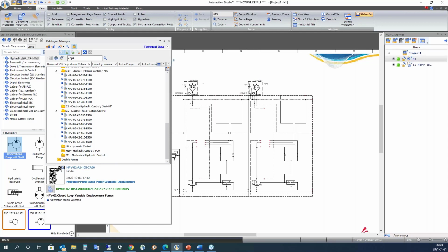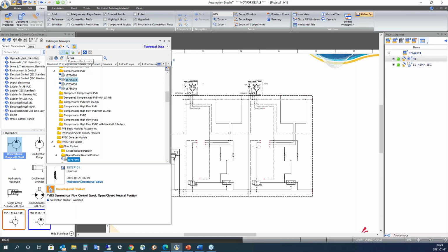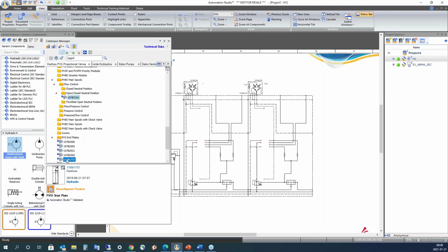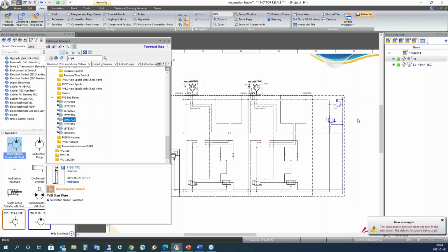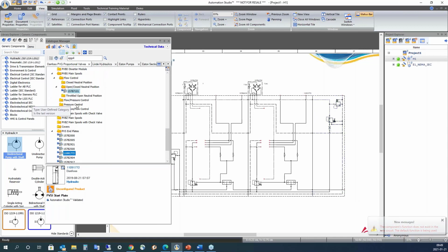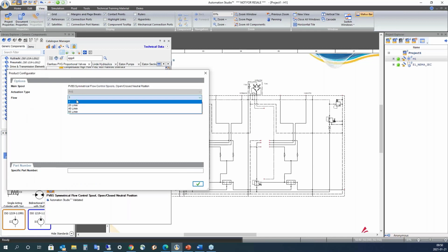So let's go to the right end plate. So end plate, I selected that one before. That was this one. And there you go. I have the right plate and the spool. So I will have to select the main spool. So the spool is here. You have to configure. With this configurator, I will be using one set at 40 liters per minute.